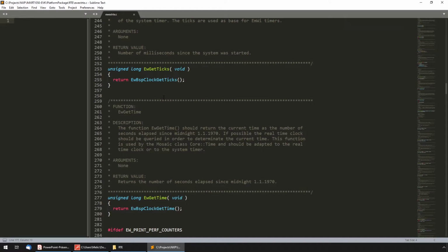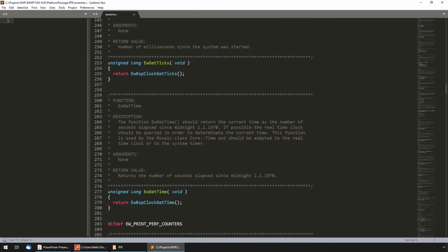This functionality is essential to implement, due to the fact that based on that time, animations, effects, transitions, and these kinds of time critical things are implemented. Also touch recognition and gesture recognition from touch input. If we do not have a proper time base, then we cannot do the proper calculations of the previously mentioned elements, and things get very spooky, or could get very spooky, if the time base is not correct. So this is the place where you would add the proper tick mechanism.